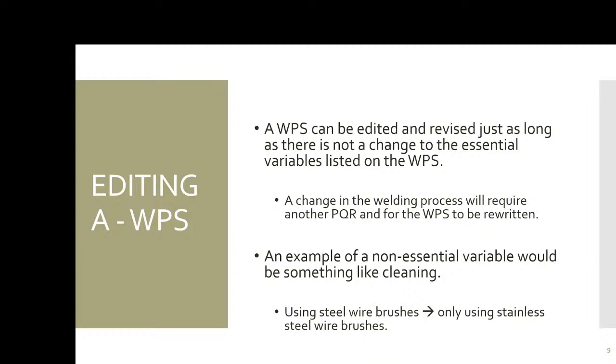Well, that's not going to change the mechanical properties of my welds. But if I change the filler metal from carbon steel to stainless steel, that's an essential variable. I've got to requalify.